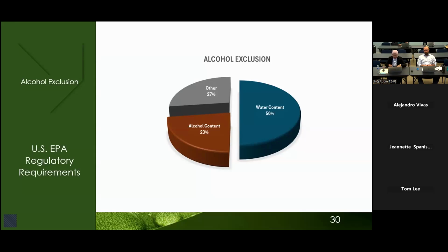So, by replacing the broad term aqueous with a clear 50% water by weight, it's easier for waste generators to know if this exclusion applies to their waste. With all this talk about aqueous solution versus 50% water by weight, it becomes clear why the US EPA's modifications for this rule help simplify things. This refined definition helps identify most water-based solutions, which tend to be lower in fire risk, and makes it easier to apply exclusions consistently, while California is still carrying the undefined term aqueous solution into its regulations.